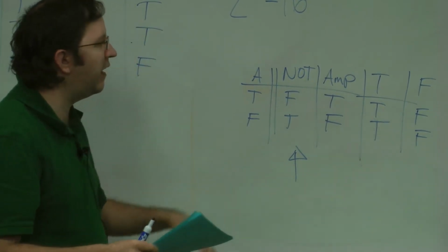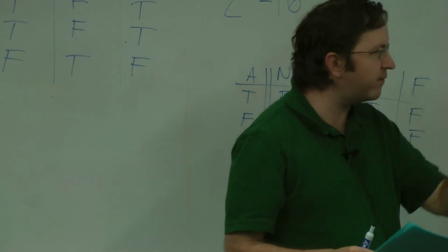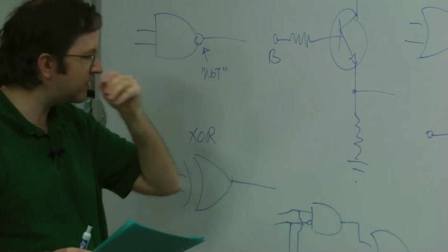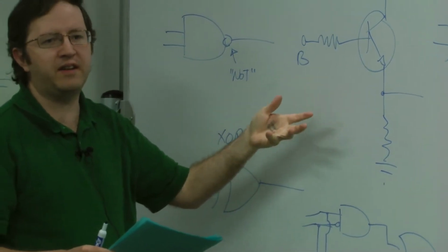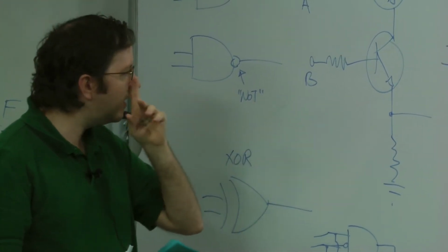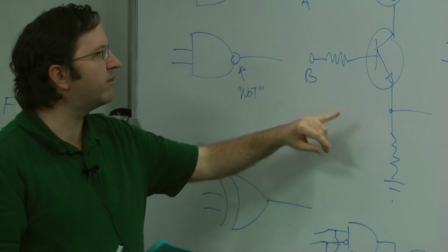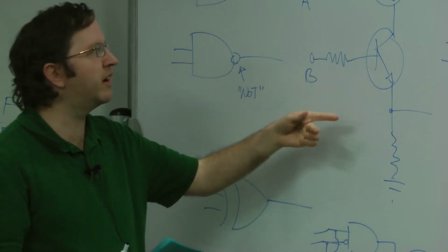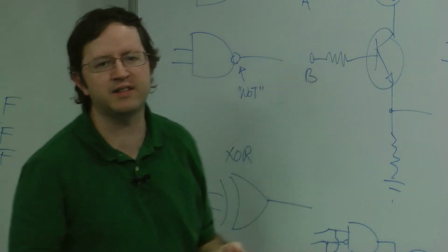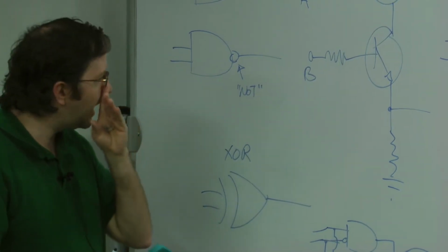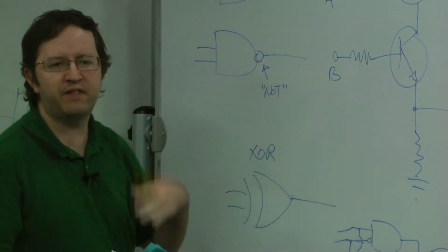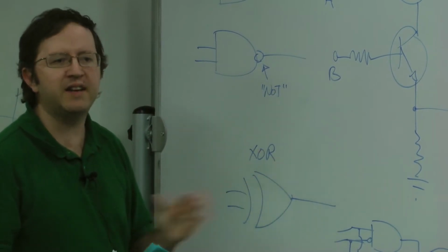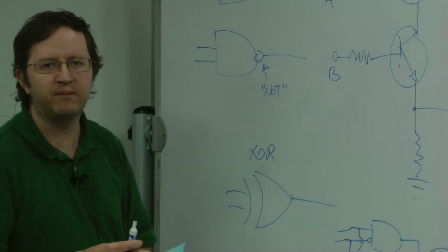And there's one other thing that should be pointed out: if I were to replace these NPN transistors with PNP transistors, it basically flips the circuit. Instead of being positive logic where everything is expected to be plus 6 volts, everything would become negative logic, and so we'd be using negative 6 volts for the circuits instead.